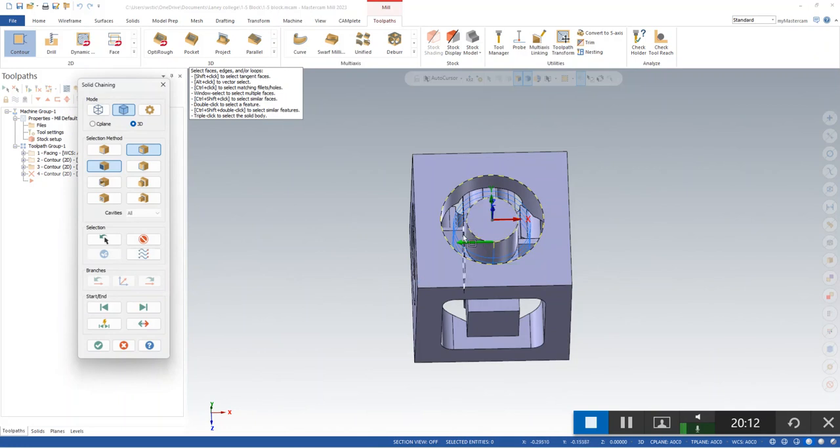Alright, so you got to make sure that the inside circle is pointed clockwise, the outside is pointed counterclockwise. Alright, so now if you click at it and it's pointing the wrong way, you can hit the reverse right here. Over here, reverse. Okay, so make sure you got it pointed the right way. And then green check.